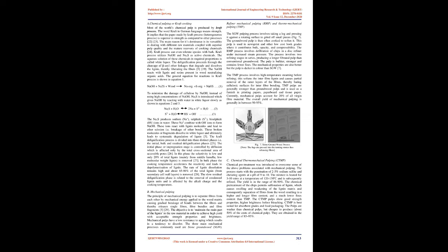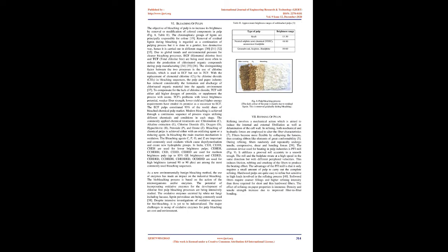The Na2S produces sodium (Na+), sulfide (S2-), and bisulfide (HS-) ions in water. These Na+ combine with OH- ions to form NaOH. These ions react with lignin molecules and lead to etherolysis, i.e. breakage of ether bonds. These broken molecules or fragments dissolve in white liquor and ultimately lead to systematic degradation of lignin. 5. The Kraft delignification process is divided into 3 distinct phases, i.e.